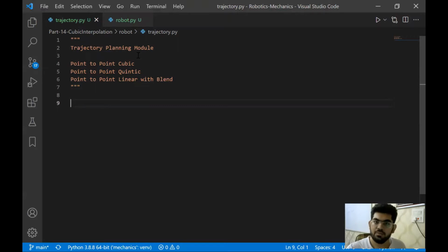And trajectory planning can be done in two ways. These are the obvious two ways that one can think of. Either we can do it in the joint space, where we set the joint positions one by one, or we can do it in the Cartesian space, where we measure the points that are on the path, convert them back to joints and then interpolate the path. Both of these methods have their own pros and cons.